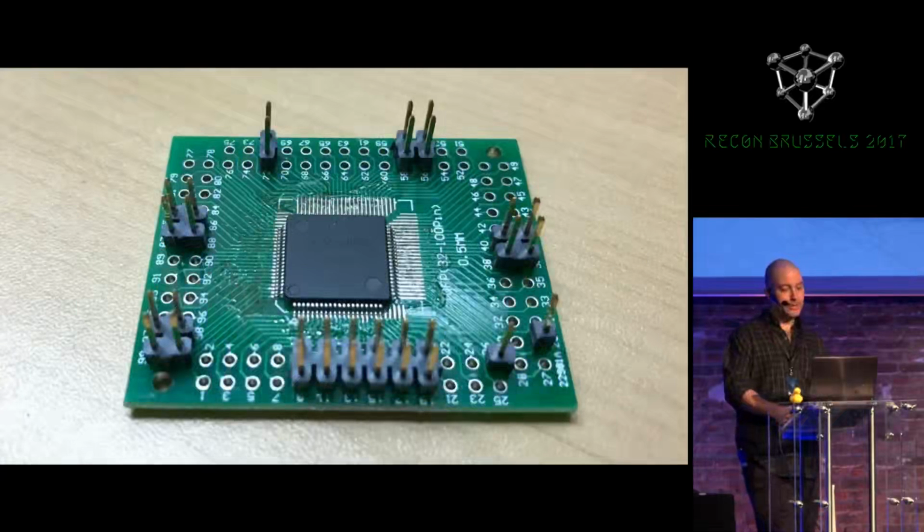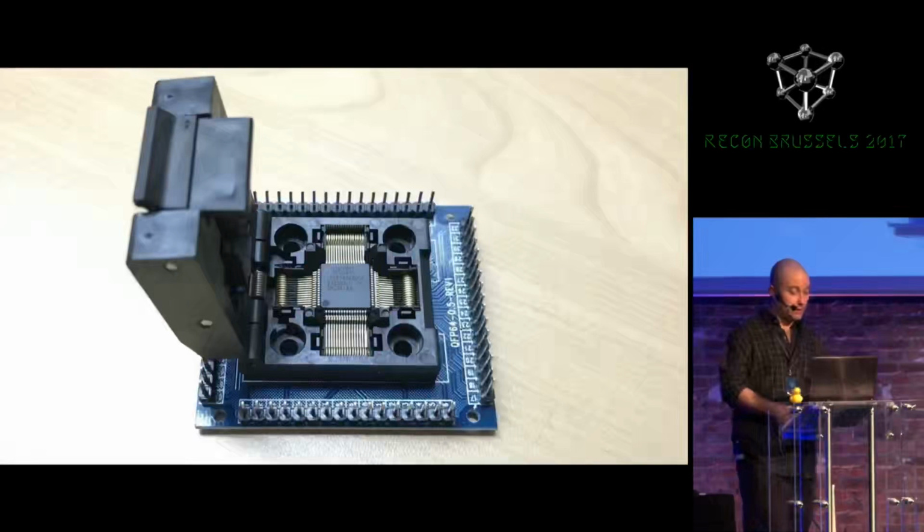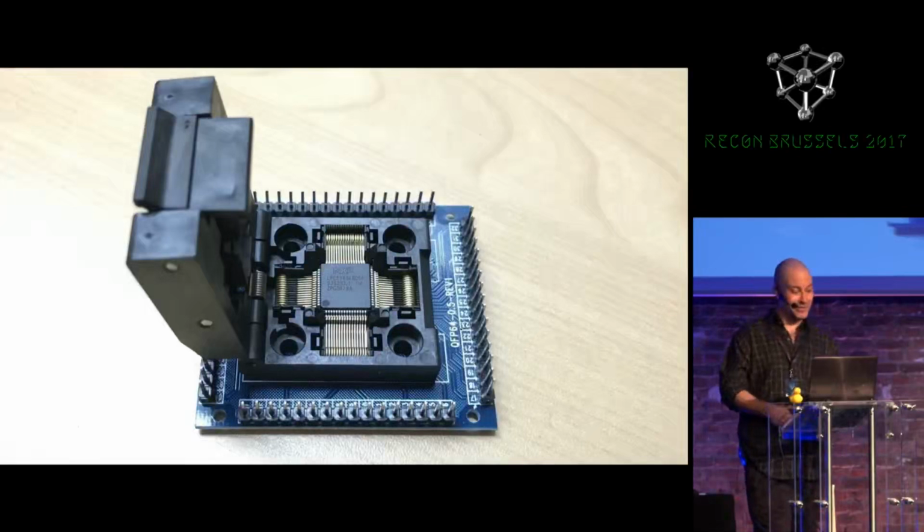This is the LPC 1751, and you can see I've only populated some pins on the breakout board. This is because really I only need to power the chip to enter the bootloader mode and to have the serial access. I'm not interested in so many of the other peripherals, so I try to keep it simple. This is an LPC 2101, another member of the family. And this is an LPC 2148 on a nicer breakout board that I found with a ZIF socket. That's a lot more convenient to work with if you're going to be changing between a lot of different chips.